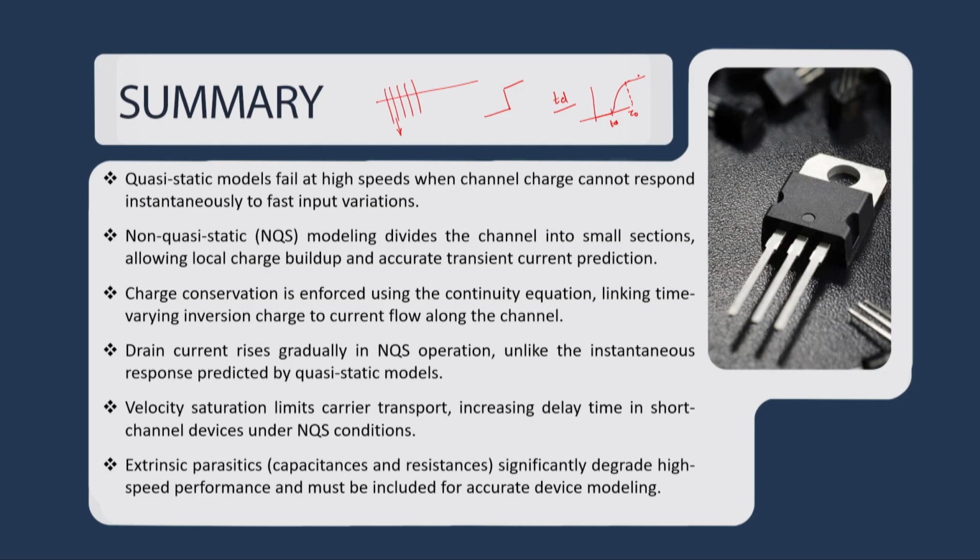In addition to the intrinsic part of the MOSFET, we have also seen that the extrinsic part of the MOSFET, which is nothing but extrinsic capacitances and extrinsic resistances, governs the overall MOSFET operation. And hence it is very important, when you are using this device in analog or digital circuits, to properly model the effect of extrinsic resistances and capacitances for proper operation.